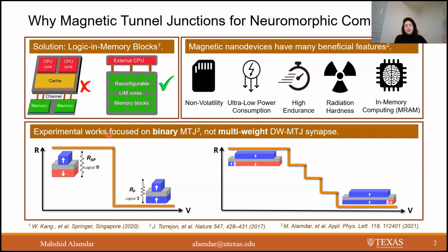In the brain, synapses, as one of the two main building blocks of neuromorphic computers, control the degree of connectivity between neurons by having multivariate conductance states that can be set based on inputs from neurons. The fundamental requirements of a synapse are the abilities to change and store its states. By leveraging the non-volatility of magnetic tunnel junction, the synapse provides the memory required to store the synaptic weights. But how about changing these states?